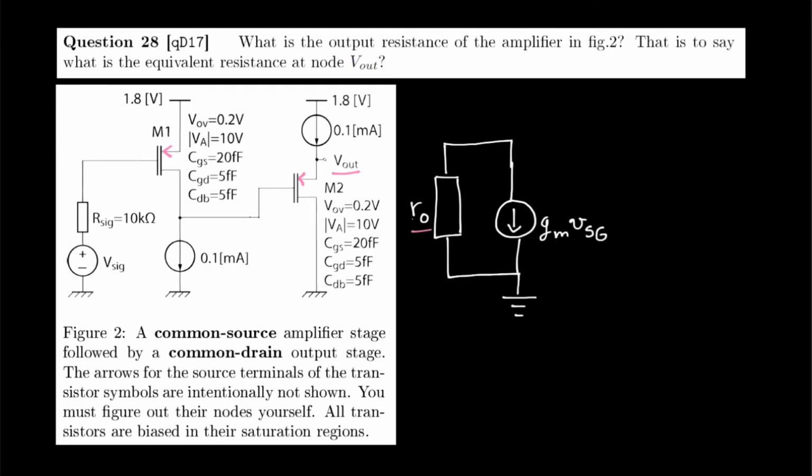If we want to measure the full output resistance, we have to take a voltage source at the specific node where we want to measure the output resistance and inject a voltage in there, so a test voltage, let's say Vx, like this. And then we measure how much current will enter the circuit, Ix. To then get the full output resistance, we can just divide Vx by Ix.